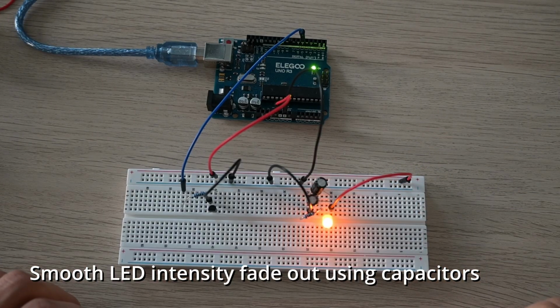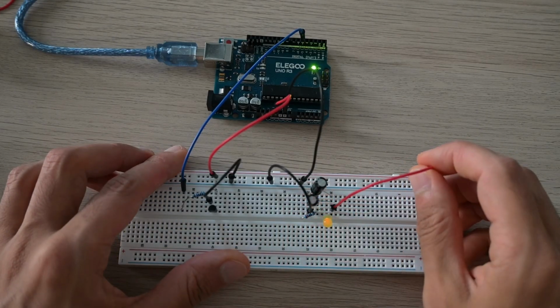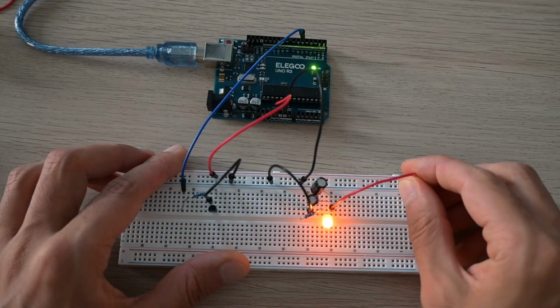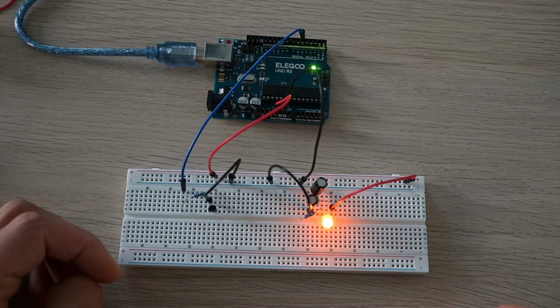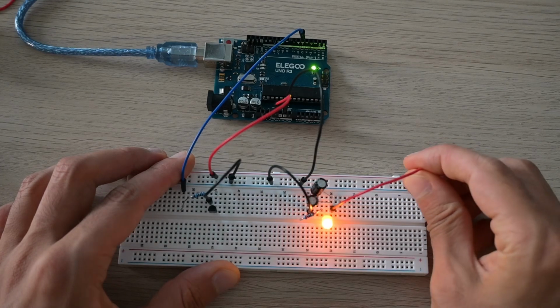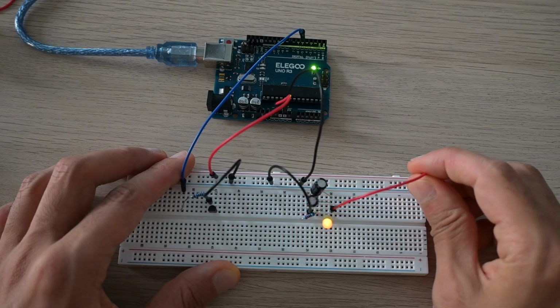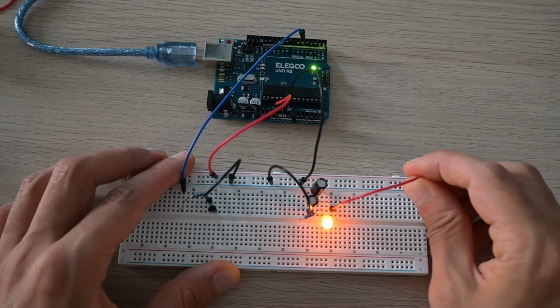Now, if we grab the same circuit that we had before to light up a LED and place one or more capacitors in parallel with the LED, once we power the circuit, the LED immediately lights up and the capacitors charge in tandem. But once the main power source is removed, the capacitors start to smoothly discharge into the LED, creating a smooth fade out of their intensity.